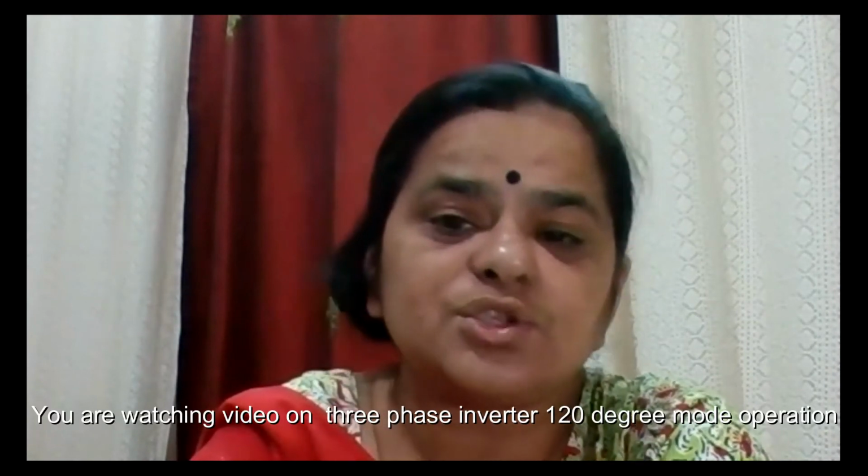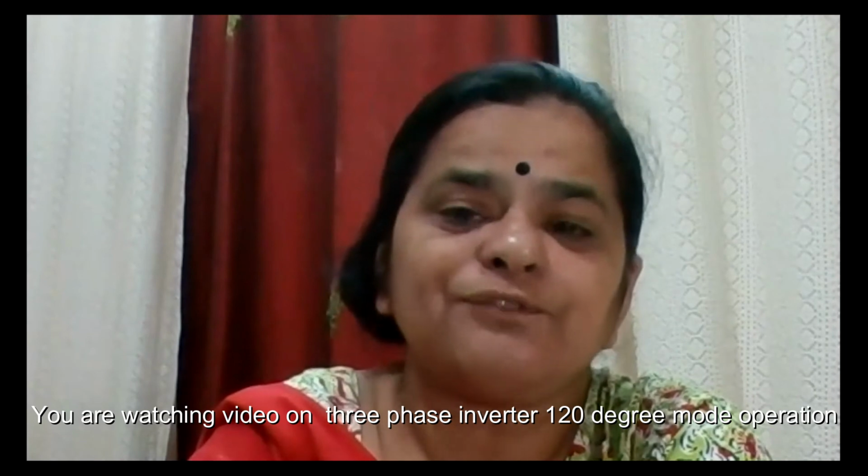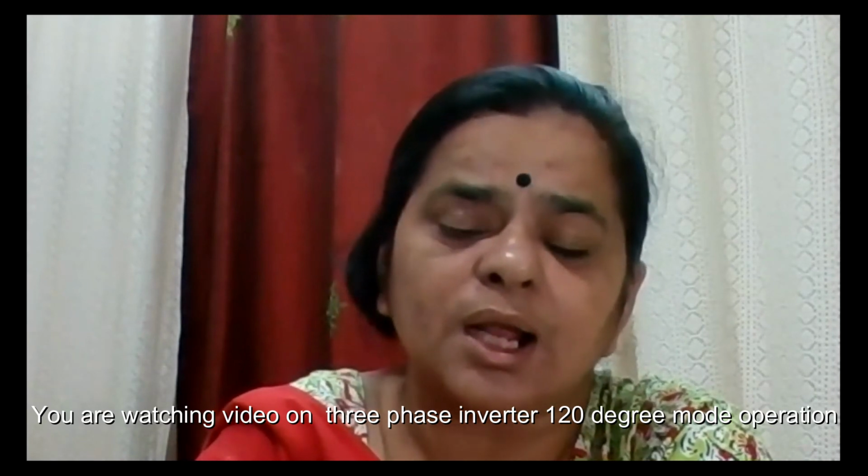My dear friends, I just want to tell you that in a three-phase inverter, if we get the output in a greater number of steps, the waveform will be closer to the sinusoidal waveform. Like in 120-degree mode operation, we have seen that in phase voltages we were getting a 3 level output voltage waveform, and if we see the line voltages, that will be a 4-step output voltage.